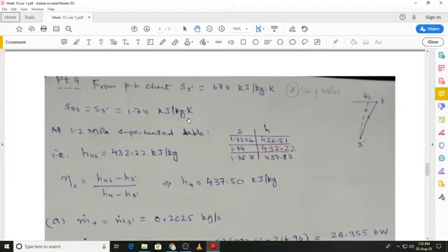And this time, because we already have a value of 1.2 megapascals in the superheated table, the interpolation is just a one-step process. That means we only have to find out the enthalpy at the given entropy. So we have the entropies in the table of values 1.7226 and 1.7571, and the entropy that we have to work with is in between these two values.